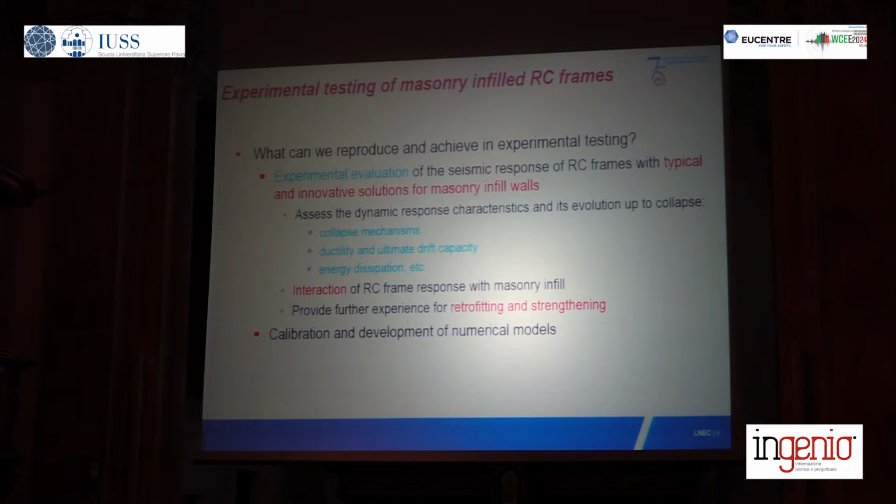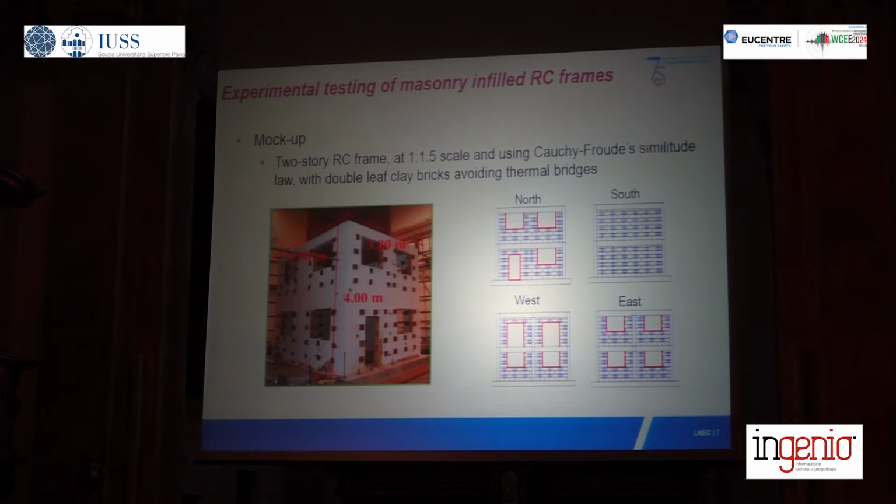In terms of experimental testing, what can we reproduce of this behavior and achieve in experimental testing? So we are looking to assess the response in terms of collapse mechanisms, in terms of ductility and ultimate drift capacity, in terms of differences in energy dissipation, and the interaction between the frame and the masonry infills. I will also be showing some examples of retrofitting and strengthening solutions for the masonry infills.